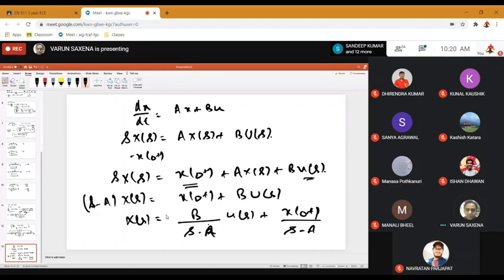If there is R and C, then voltage across the capacitor is going to be the state variable. If you have R and L, then it is the current across the inductor. If you have R, L and C, then the current in the inductor and the voltage across the capacitor are going to be state variables.